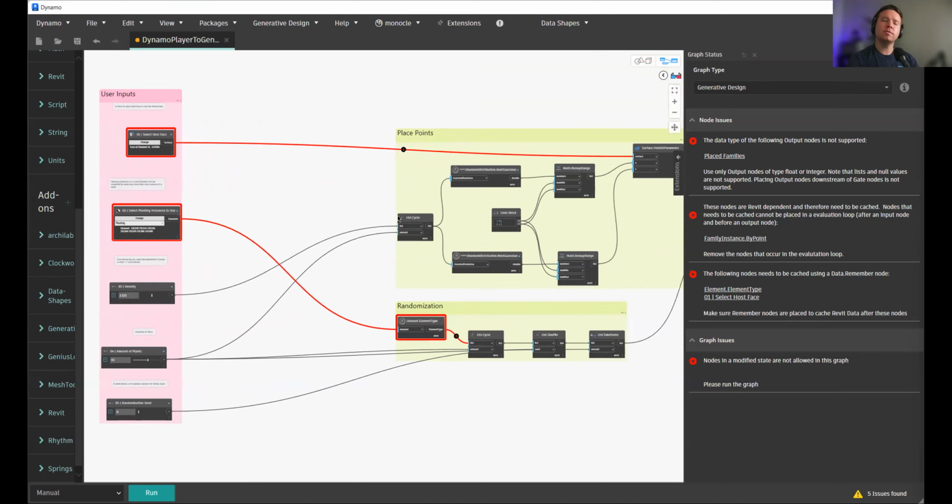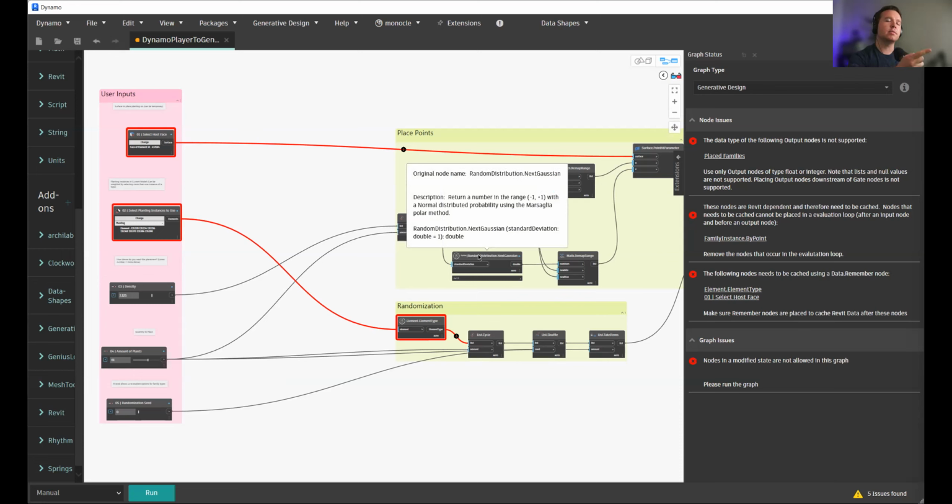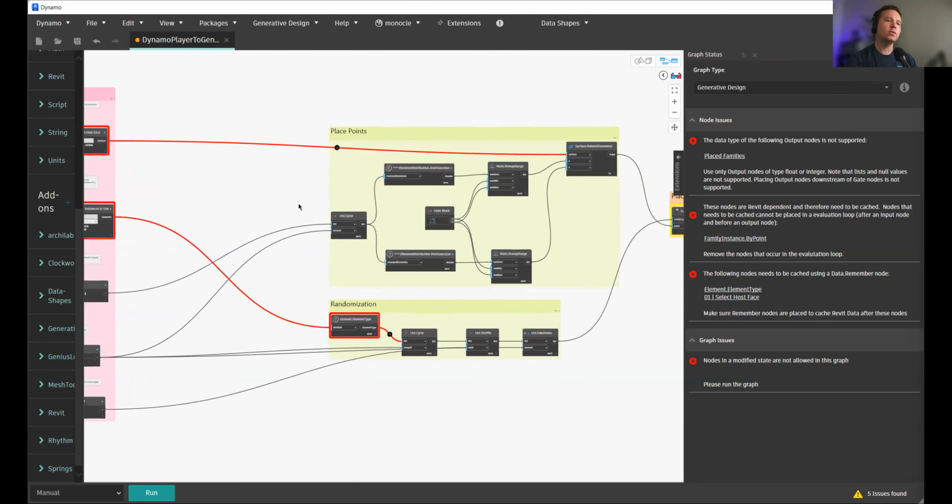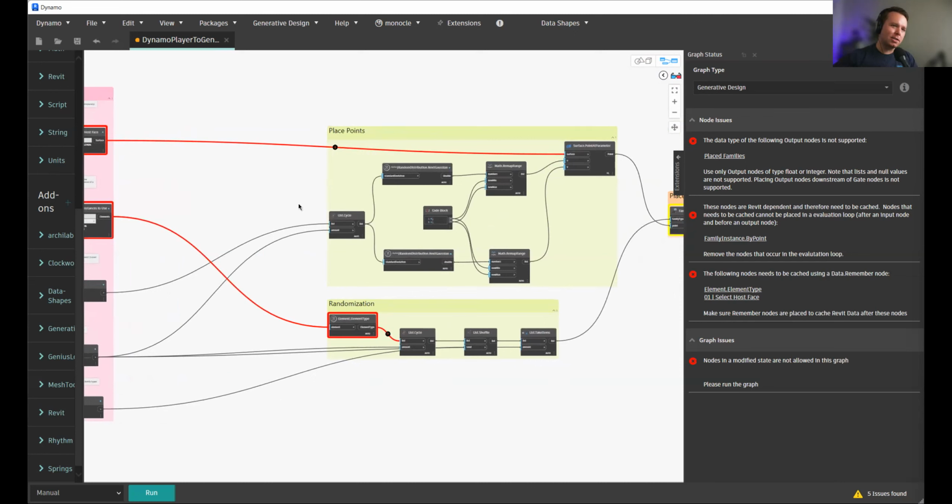So in the case of generative design, it runs 4 instances of Dynamo in the background while it's optimizing or randomizing or something like that. You can actually see that in your task manager if you run it while running generative design. So that's how it helps optimize things so well, which is really cool. I wish we could do that with Dynamo to where we just fire off 4 instances, let it solve and come back. That'd be pretty cool. But it does that for generative design.